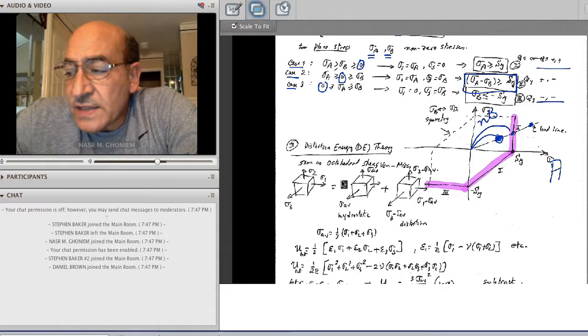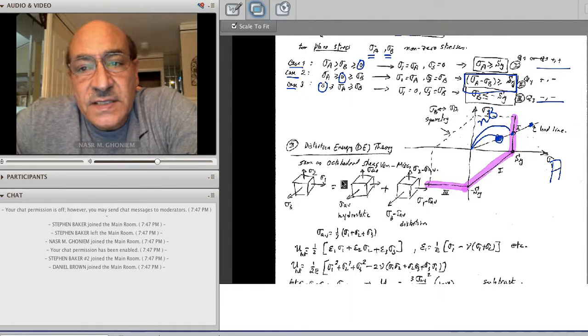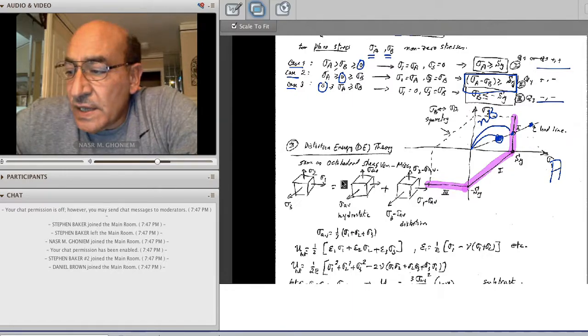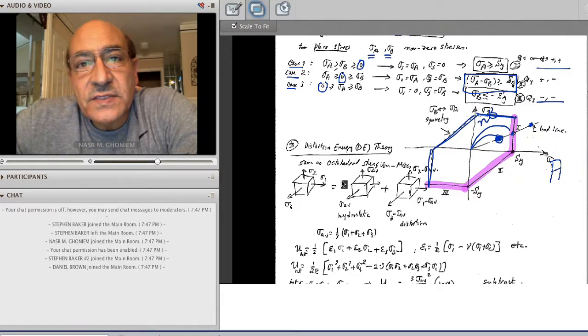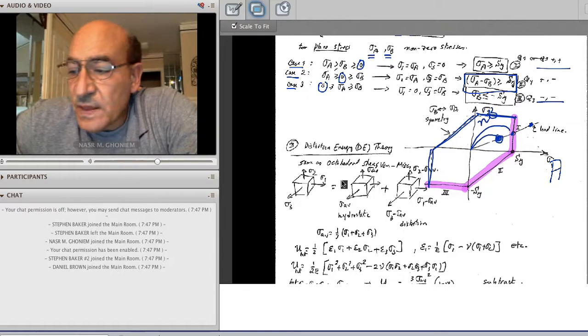If the point is outside, then we have a factor of safety less than 1. And then we complete the rest of the boundary by symmetry, because we don't have any reason to say that compression is different from tension for a lot of ductile materials. So that would be the yield surface, or the Tresca criterion.